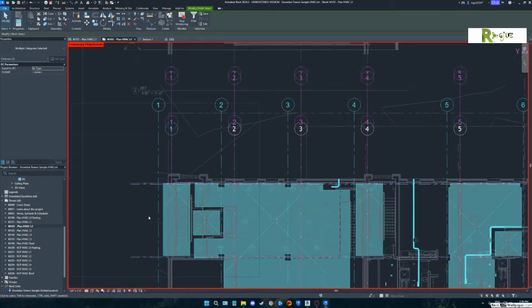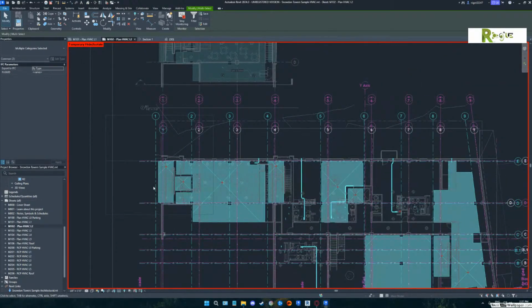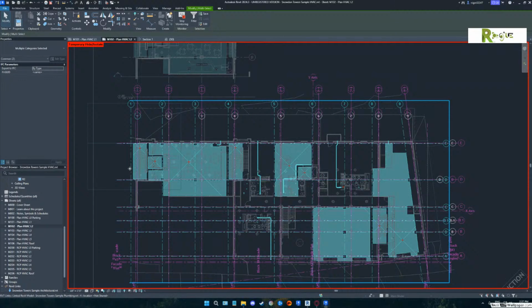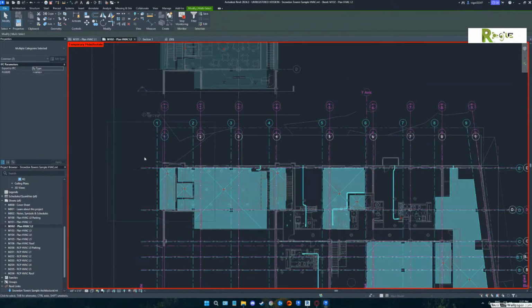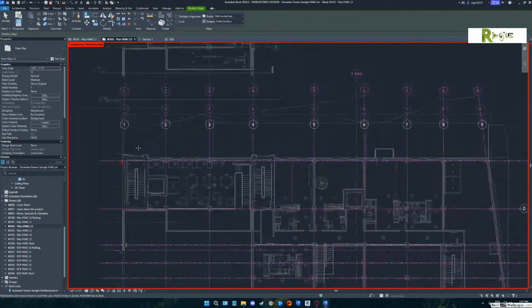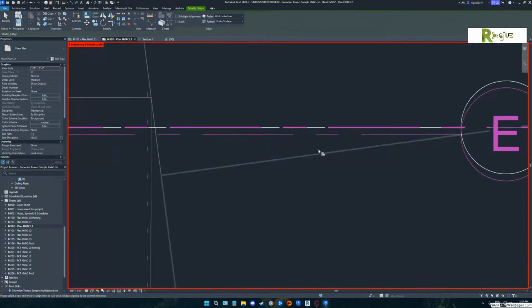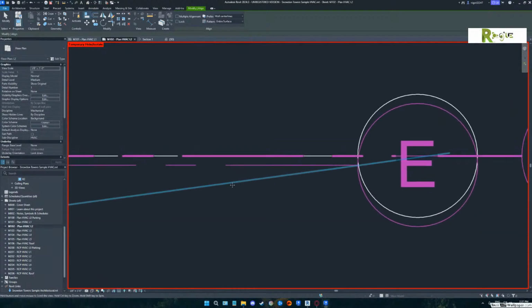Now all you would do is an alignment. It's double escape. And you would align your white grid line to that level 1, to the number 1 in the purple over beside it. And then you would go down to your E, A, B, C, D stuff on the side and get one of them. Zoom in real close. You'll see one of them is slightly off. The white is the good, the pink is the bad.